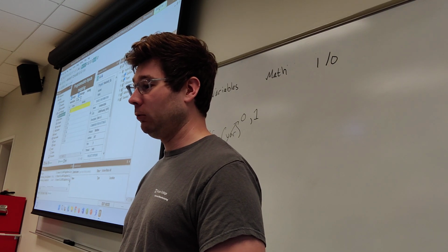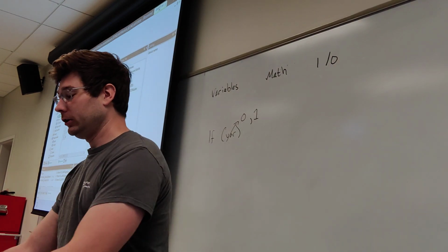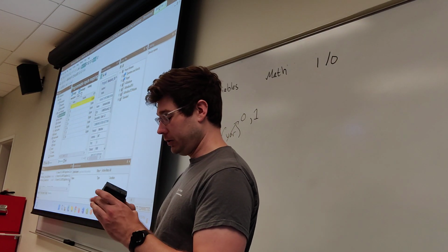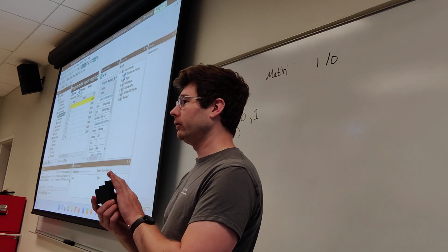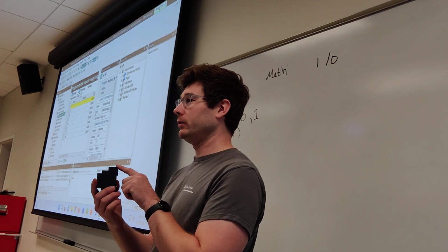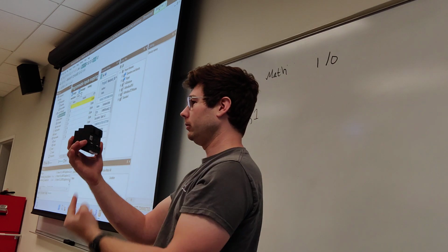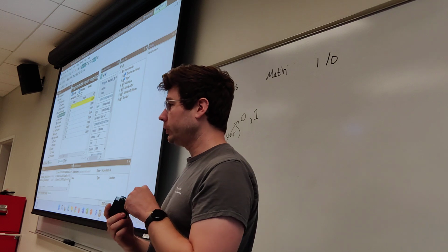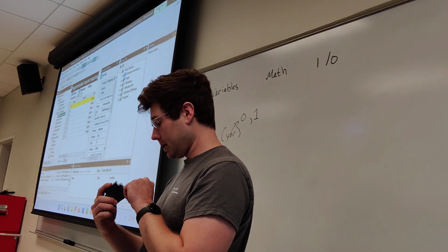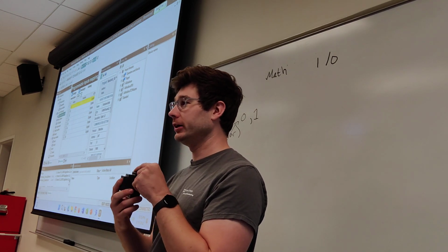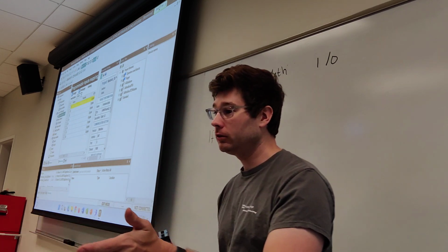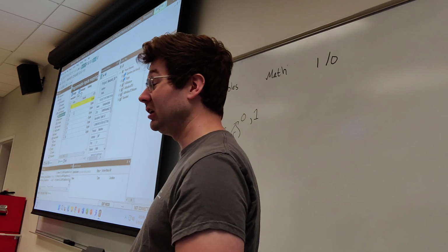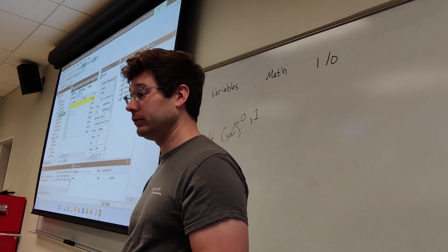Okay, this is where the rubber meets the road in terms of assigning variables to physical space. You guys remember that our inputs to the device, where our sensors go, are on the top of the device. All of our stuff goes in the top and goes out the bottom of the PLC. Also note, please look at your PLC and see that I1 through I8 is printed on there. You guys also see, I hope, inside of our programmable inputs mapping list, we also see I1 through I8. You can probably see where this is going.